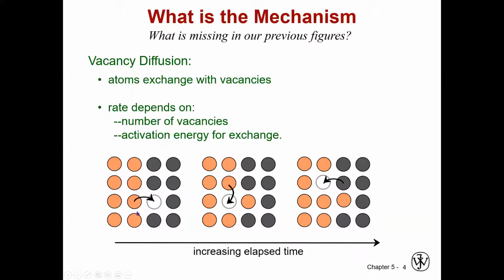Let's say a few other things we want to say about this. This particular sketch makes it appear as if any of these atoms would just fall into the hole. There's no reason why this atom would stay here if it can move over into this one. In reality, this lattice is tighter, and when there's a vacancy here, this whole region will relax inward a little bit. And so in order to move one of these atoms into the hole, it will actually first have to kind of push atoms out of the way.